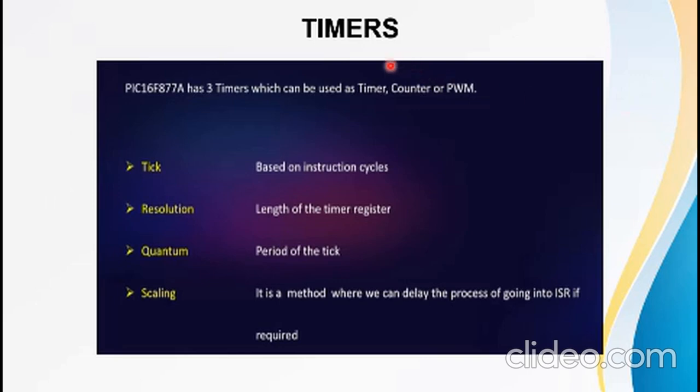Timers. PIC16F877 microcontroller has three timers which can be used as timers, counters, or PWM. Tick, based on the instruction cycle. Resolution, length of the timer registers. Quantum, period of the tick. Scaling, it is a method where we can delay the process of going into ISR if required.